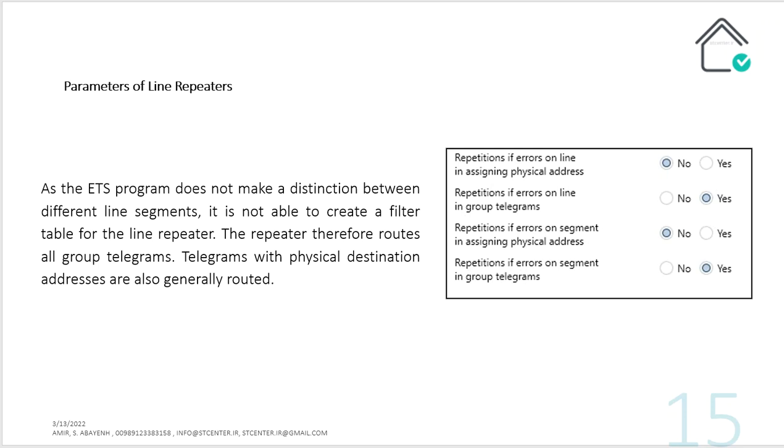But the line repeater is only the amplifier in the old topology. From the topology 2020, we do not have line repeater anymore, okay? So with the new devices, if it is written in a datasheet, you can put 256 devices in one line. That's it. But for the devices in the past, older than 2019 or 2020, if you want to put more than 64 devices in a line, you should use the line repeater.